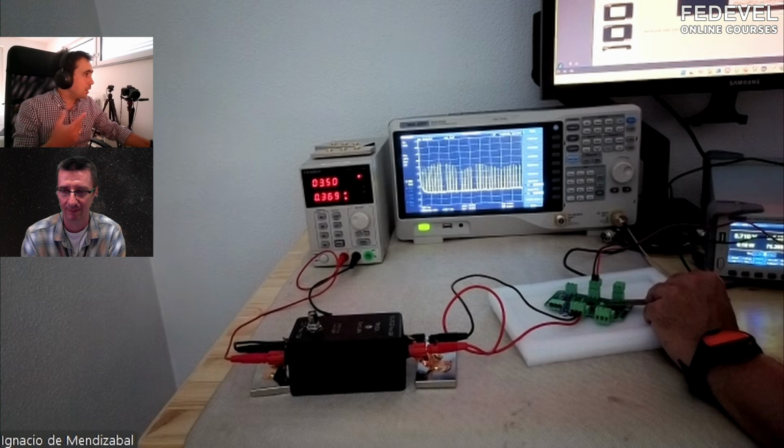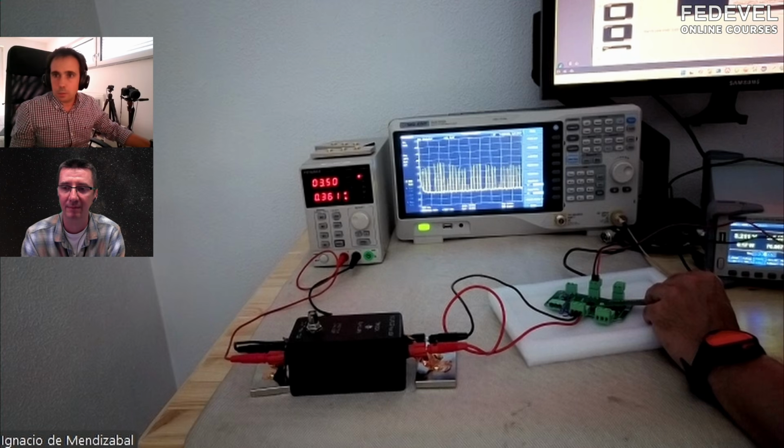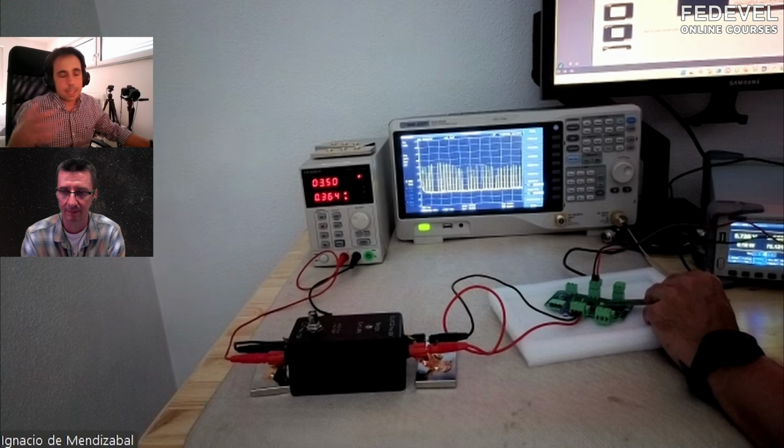And second, I'm not finding 1.6 anywhere. So what I will do is, first, I will take the oscilloscope and measure really to see if the converter is really switching at 1.6 or not, and then measure the switching frequency. Because from there, what I can do is correlate these measurements with the actual switching frequency, and from there I can extrapolate more data in the lab, in the EMC lab or here,